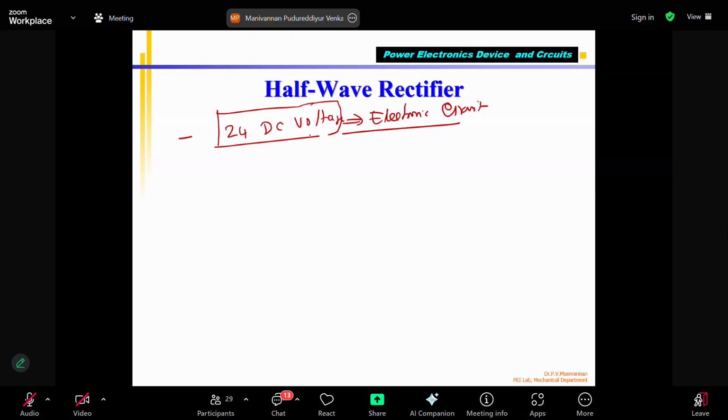Please note that somebody asked this in an interview: you cannot supply AC voltage as a bias voltage for any electronic circuit. Transistor amplifier, FET amplifier, memory IC, or CPU, correct? Embedded controller, your i7, all these things. 99% of working electronic circuits require a DC voltage as a bias voltage. Already we saw VCC and VBB for a transistor. In case of an IC, we supply voltage and ground voltage. But basically we are getting AC voltage only from the grid.